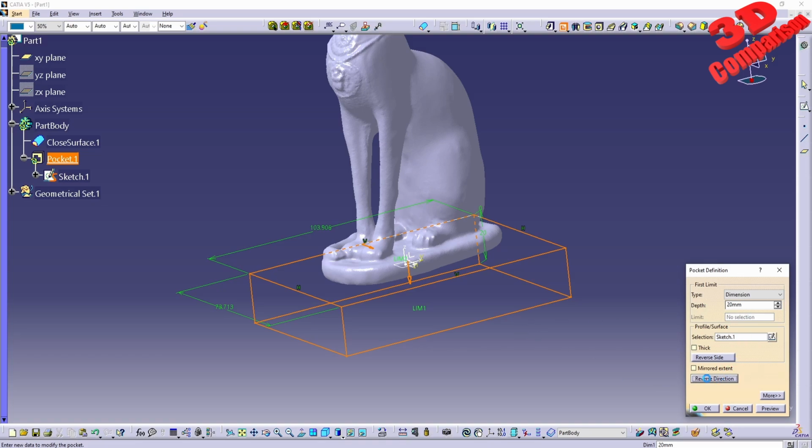And we see that even when I click the reverse direction, this takes a little bit of time. Initially, the direction for the cut went downwards, and that previewed really fast since the mesh wasn't overlapping over there. But now, since this will be overlapped over here, this will take some processing. And this is why this workflow is, again, not the best solution, and I highly recommend to use the automatic surface. But again, that requires an additional workbench that is not widely available.